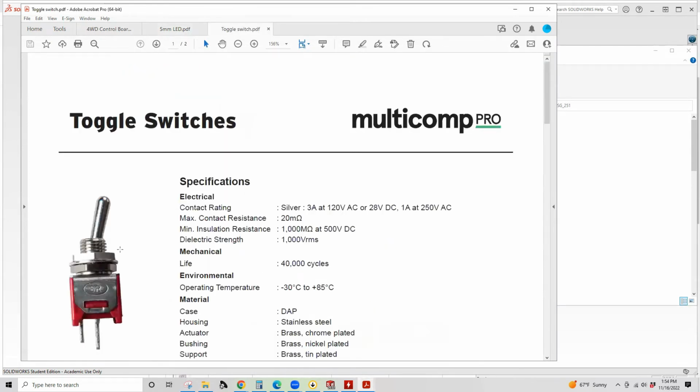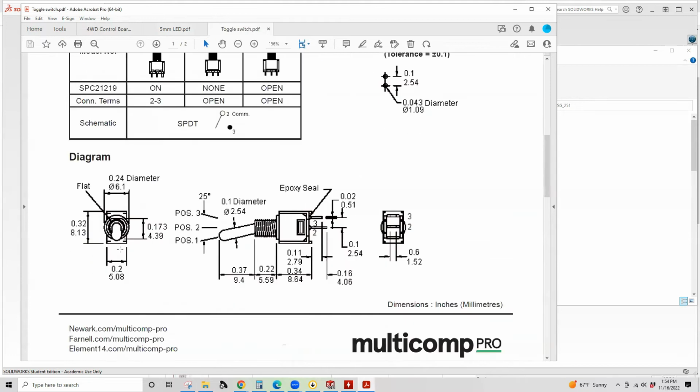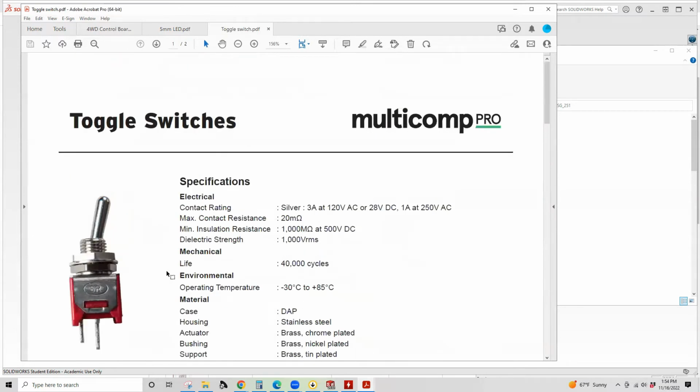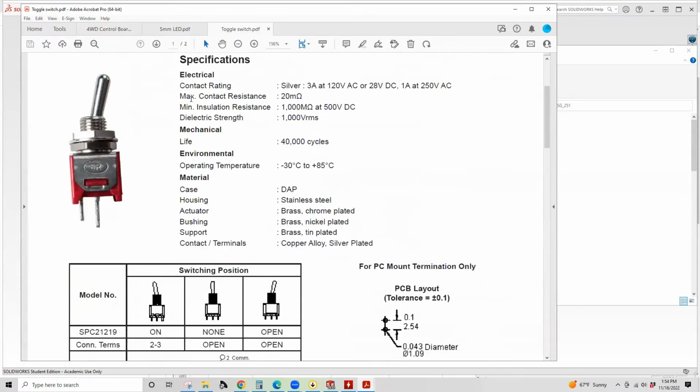One of the ones that's going to be harder is toggle switch. So this is about the same part number, more or less, as what is installed on most of the boards. These are a special category of toggle switches. These are sometimes called micro minis. So real small jobs, able to handle a surprising amount of current. So sometimes they're able to handle upwards of a couple amps down below 200 volts.